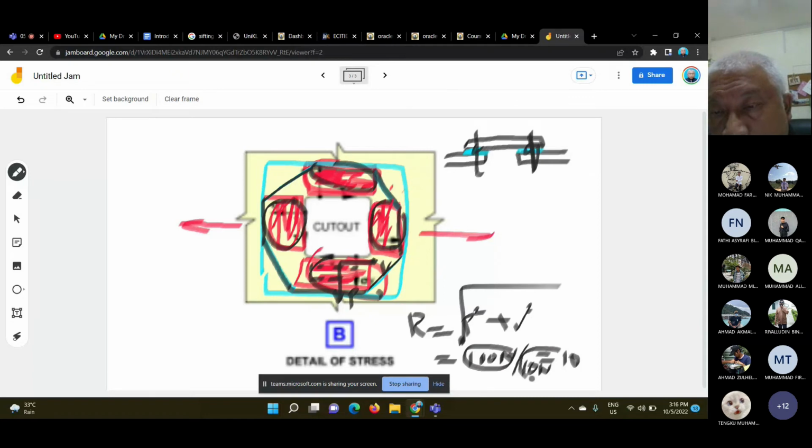How do you get this number here? You go to the repair design guideline, which gives you the strength of each rivet with diameter, the material type, and also the skin that you want to install on. They will give you the strength for each rivet diameter, which I have explained already before.